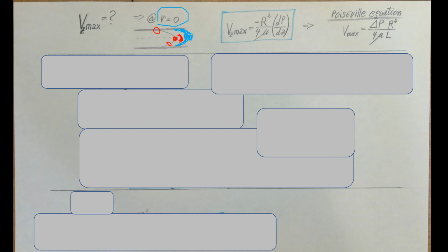So let's take our velocity profile that we have just found in our previous question. We're gonna take this data that we know for sure, plug it in, and we are able to determine that Vz is equal to Vz max, which is equal to this big pile of constants right here, minus R squared over 4 times dynamic viscosity and times the pressure term.